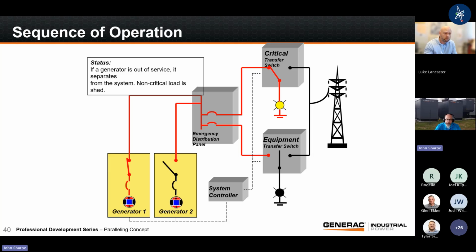So we're going to push this transfer switch to a middle or neutral dead position while we service this piece of equipment. Because my concern is this load right here is what I care about. And if I try to put both transfer switches on this gen, it may overload this gen, and we want to deal with that. So the best thing to do is to make sure that this sacrificial load stays in load shed mode until we get the second unit back.